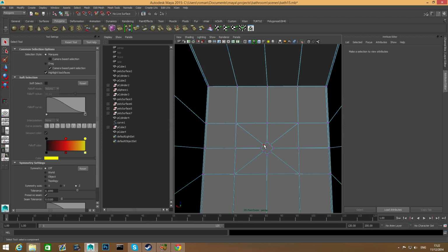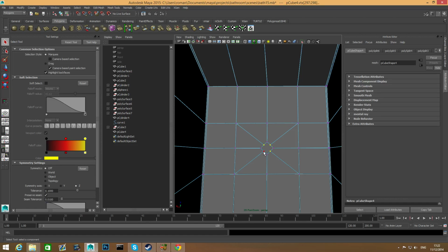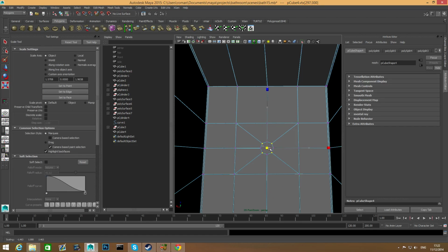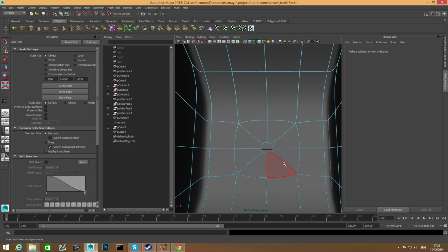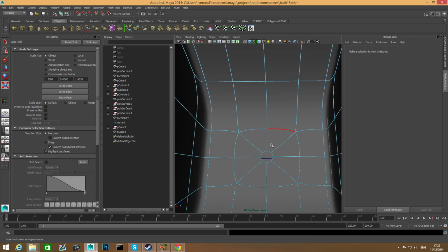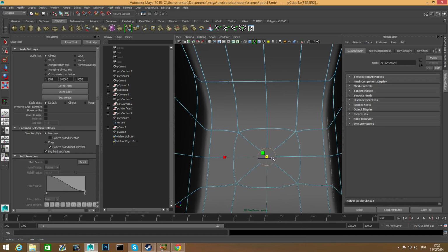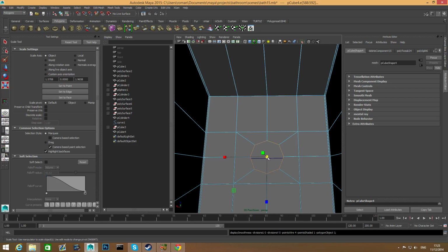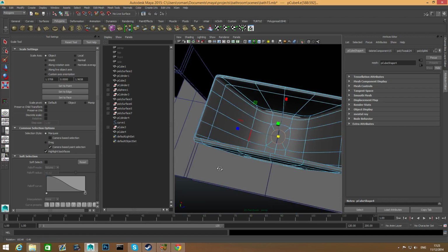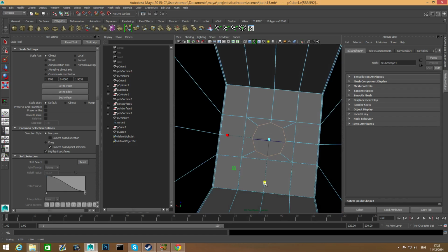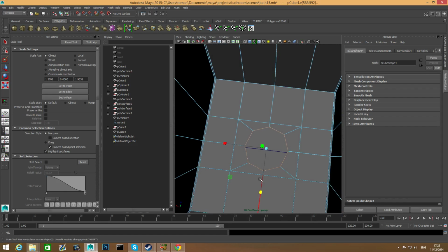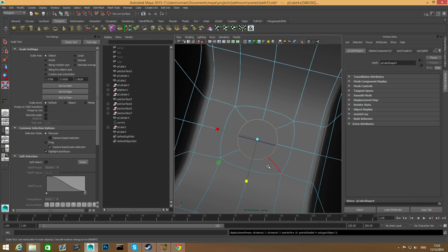Selection tool. I'm gonna grab these 4 cute vertices. Press 3, right-click, choose face. Let's grab this face and delete it. So now we have a nice circle there. Right-click, choose edge. Let's double-click on this edge, spread it a little bit. I want to do it in non-smooth preview mode, so I won't do something such as this without notice. So at least that way, I think it's enough. Okay, and maybe I will spread this at least in this size, in this direction, and yeah.